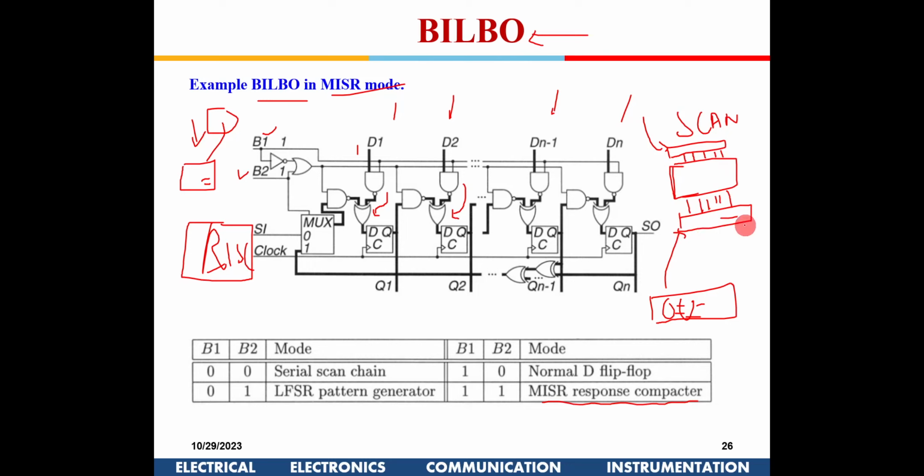Scan design means it has flip-flops. You are independently able to access these flip-flops and take data, and combined with that, the built-in test. Now built-in test is a scan design only. What we are trying to do is, instead of an external signal through the pins getting into this flip-flop, internally within the chip we are generating some random signals, putting them into these registers, taking them out, and analyzing them. So essentially built-in test is nothing but a scan test, a boundary scan test. The only difference is that the test is being generated within the chip and the analysis is also done within the chip.